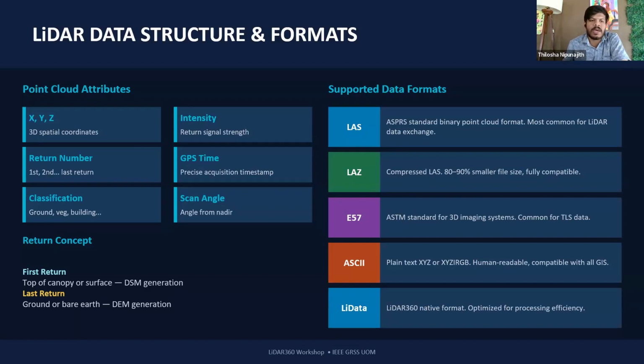You have to deal with Cartesian coordinates of X, Y, and you have to deal with the three-dimensional Z coordinate. And also you have to have an idea about the point density, and how the return signal strength can be. And this intensity tells us how strongly the laser signal bounced back onto the surface, and based on this, we can have an idea of how our 3D model can be derived to this level.